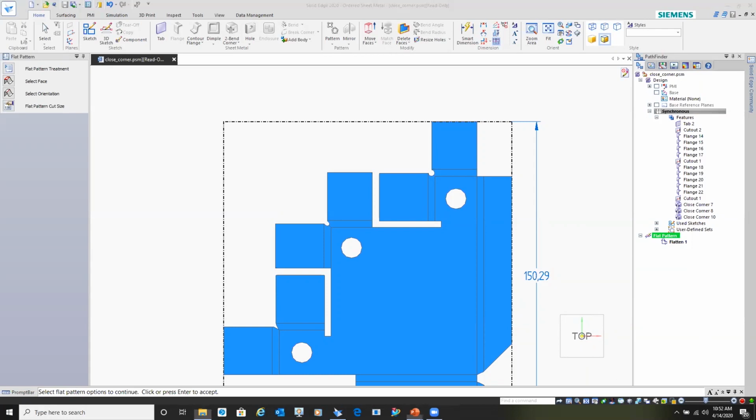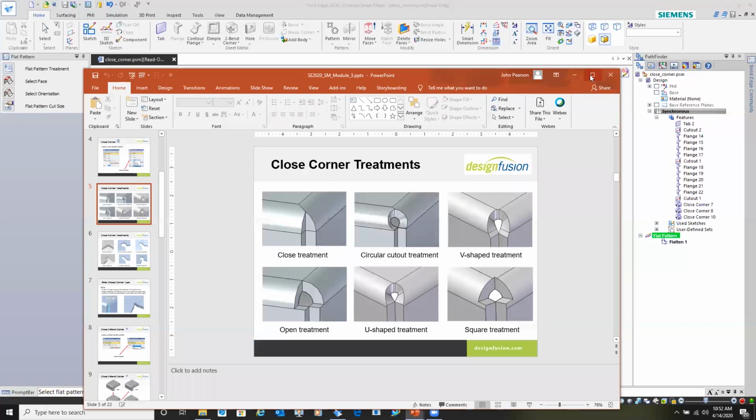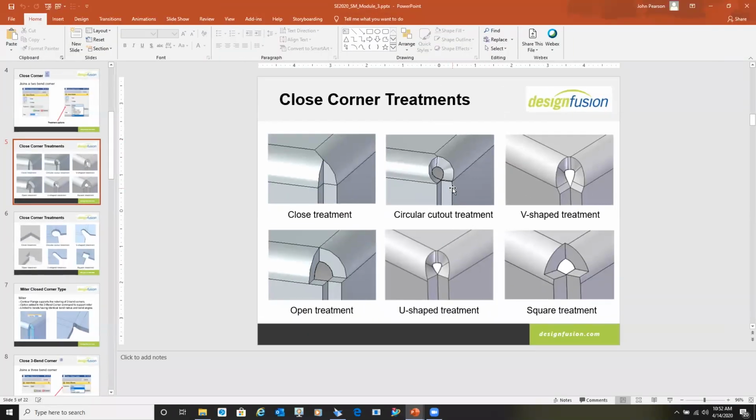And that's what I've struggled to pull off because we're required to actually have a radius at the bottom and it has to cut into the corner there so that we're not tearing and pulling the steel. Okay. And I've struggled to get that in Synchronous. And so what I've always had to do is just manually go to ordered and add it, flatten it out, manually cut my corners.